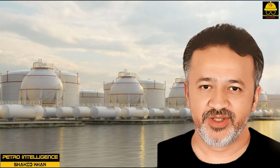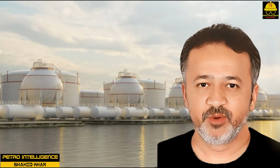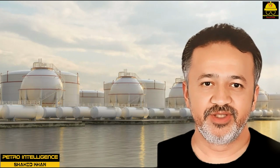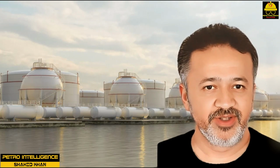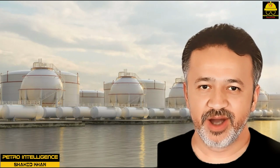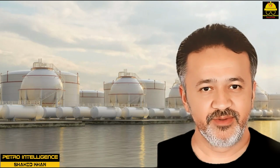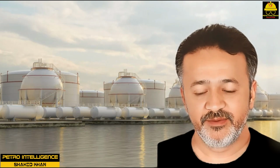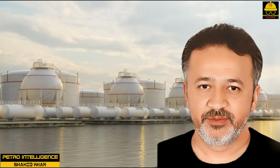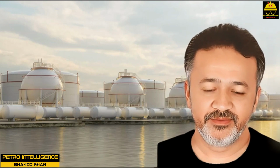A study of conditions and materials leads to planning and actual performance of inspection, at which time the true condition of the equipment is determined. The scope of inspection work also includes keeping records, reporting results, recommending repairs and methods of repair, assisting in planning turnarounds, and determining safe working limits for equipment. When inspection reveals the need for replacement parts, it is important that the new parts be designed in accordance with recognized codes and specifications.